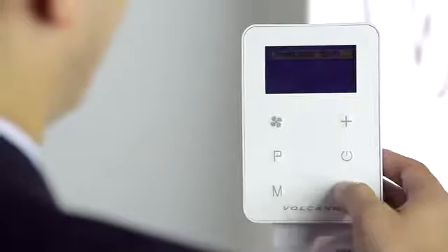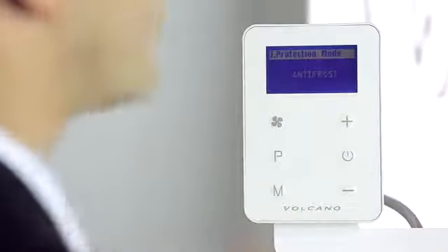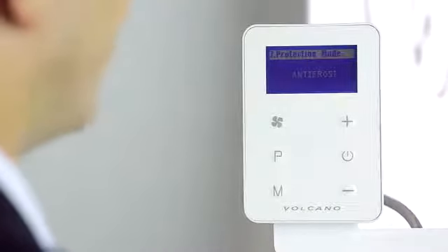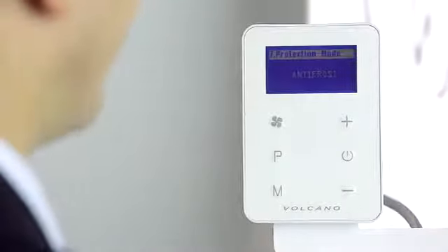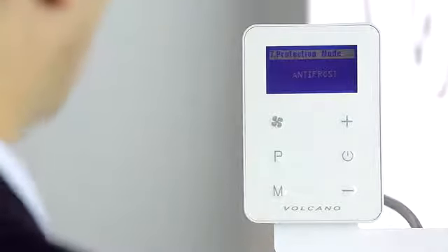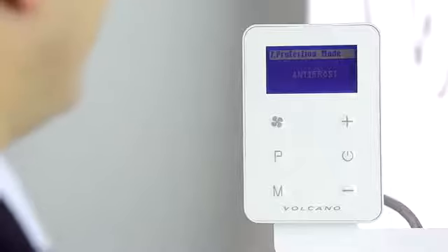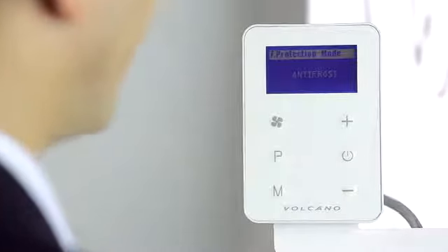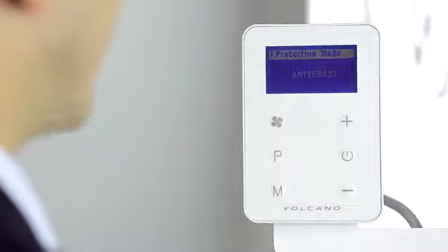The temperature we have set in setting 6 will be the limit temperature. If the room temperature falls below this temperature, the two-way valve automatically opens and allows the heating agent to reach the heat exchanger and protect it from freezing.